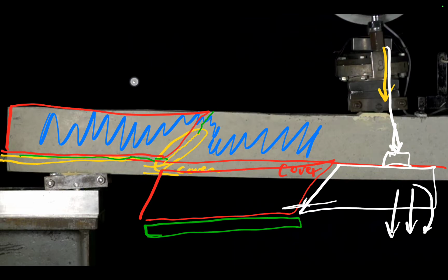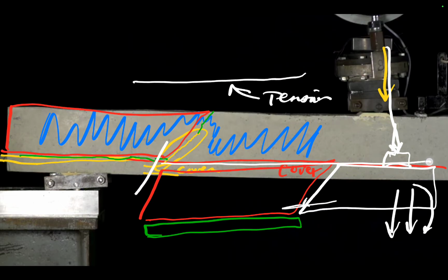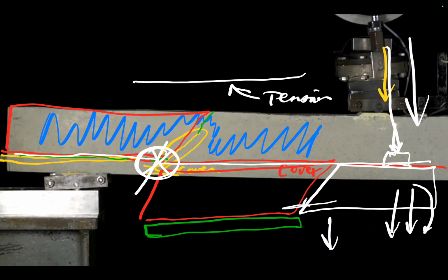So your steel down at the bottom is getting loaded, and it's deflecting, and it's being put in tension, well, for the most part, because it also has a neutral axis where it transitions from tension to pretty much no tension. It's just a rotation, and that is resolved right there, literally right here, where the first crack starts developing. That's its neutral axis of the rotation of this going down, and this section not being able to go down, met by it trying to resolve itself there.